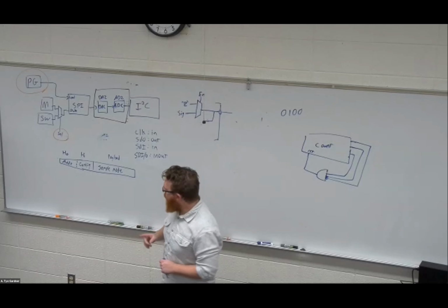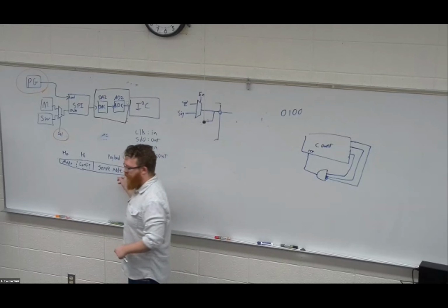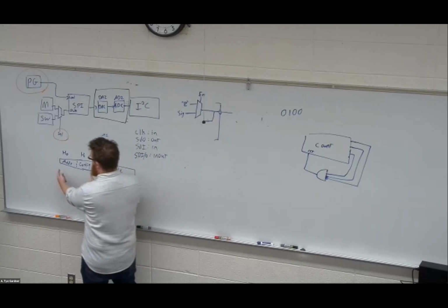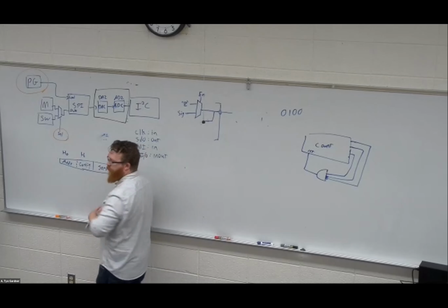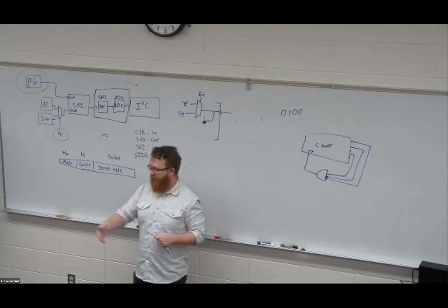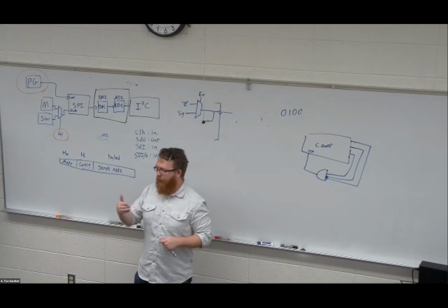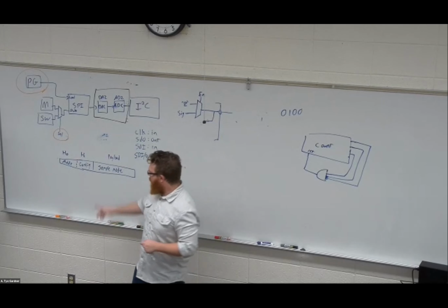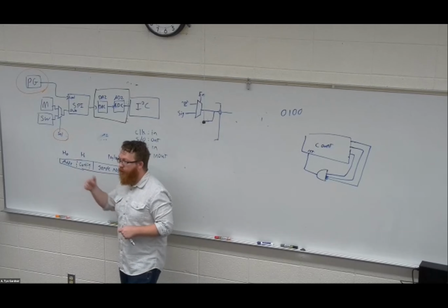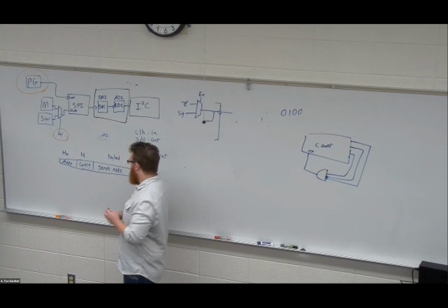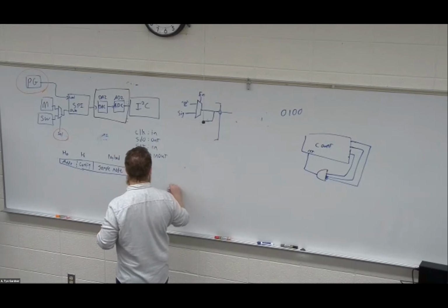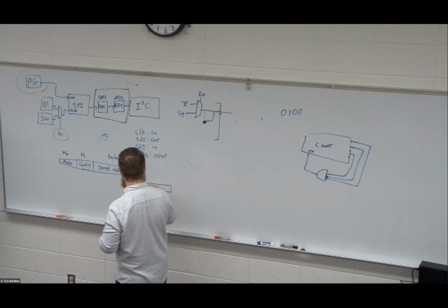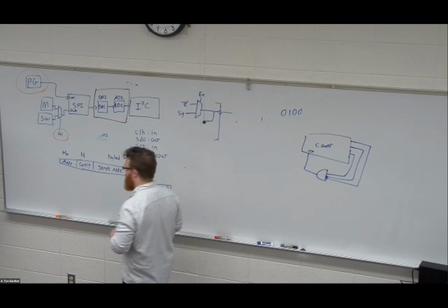The reason that you would do that is because if it goes into continuous mode, it no longer needs to send the address and the configuration, and your I2C can just sit and wait for 12-bit samples, one after the other, which means that you get payloads faster, right? So that's part of what this configuration is doing, is saying go into a certain sampling mode. Say your sample mode is single, then it's going to reply with its data sample.